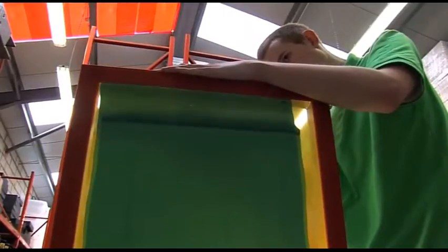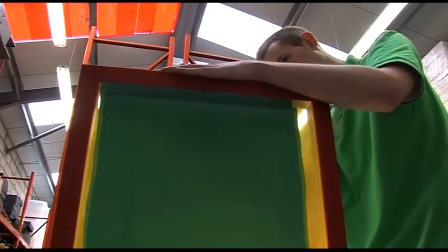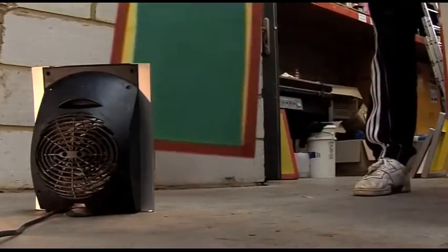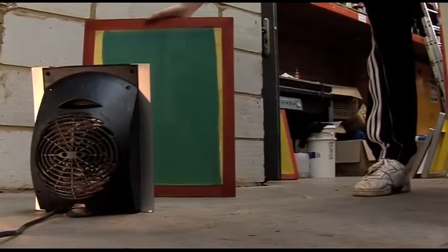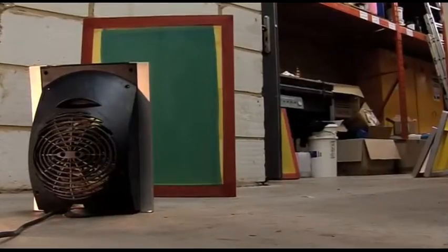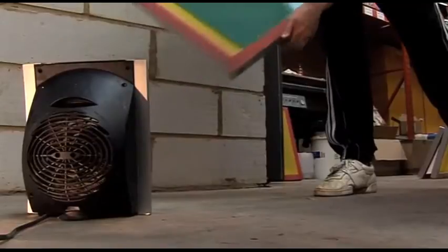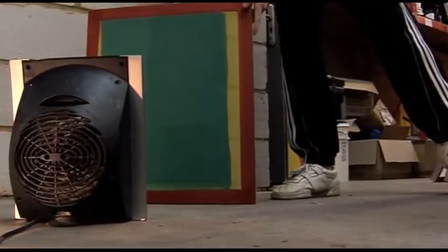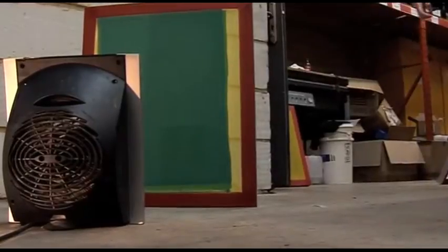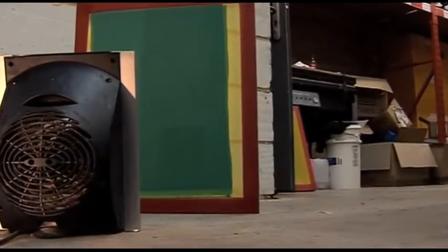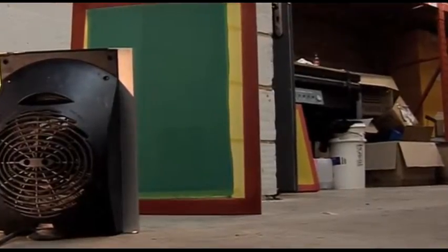The fewer coats you perform, the less of an inkwell is created, thus meaning less of an ink deposit on your garment. Allow the screen to dry for approximately 4 to 6 minutes on each side with a fan heater. Turn your screen 180 degrees, ensuring each half of the screen dries. The emulsion will change from glossy to matte when dry. We suggest not using a heating device such as a heat gun or hairdryer. This heat is non-consistent and may contain light elements.